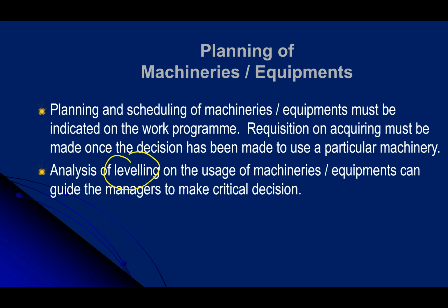Leveling, as we already mentioned in the first topic with regard to manpower, labor resource management, can also be applied to machineries. When we talk about leveling, it can be applied to man and machinery. And normally we do not do that on material because there are so many types of material, and it is very difficult to schedule the material. Even though you can do that, it is very difficult because you never know the quantity that you are going to use, because sometimes you buy in bulk and how much it goes into certain places. So you can do that, but basically it is too complicated.